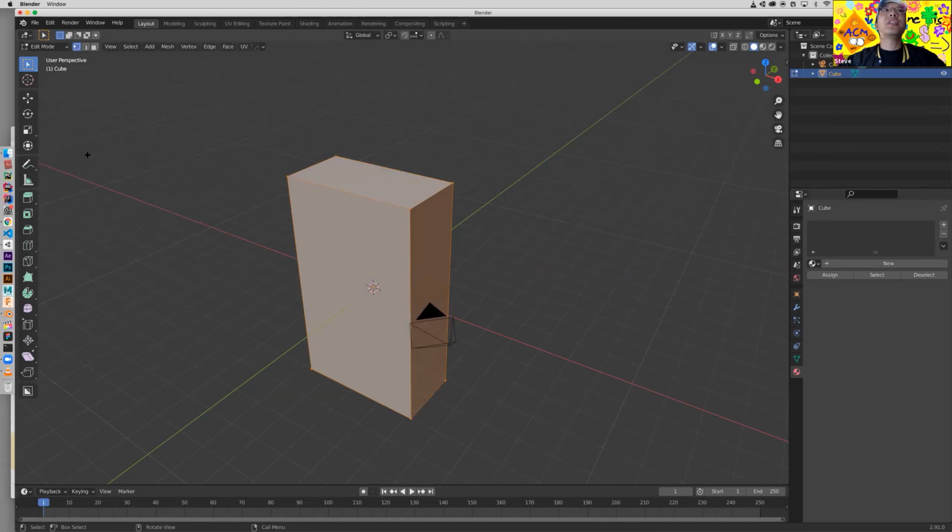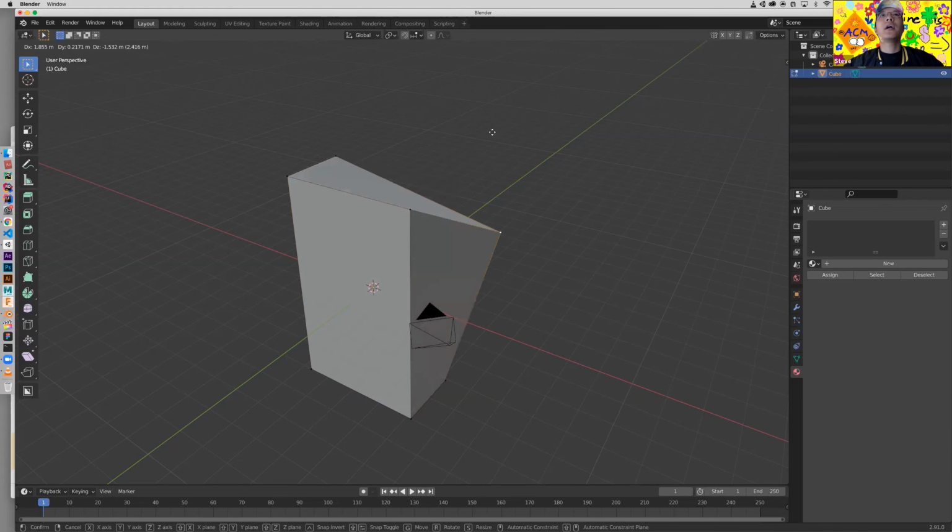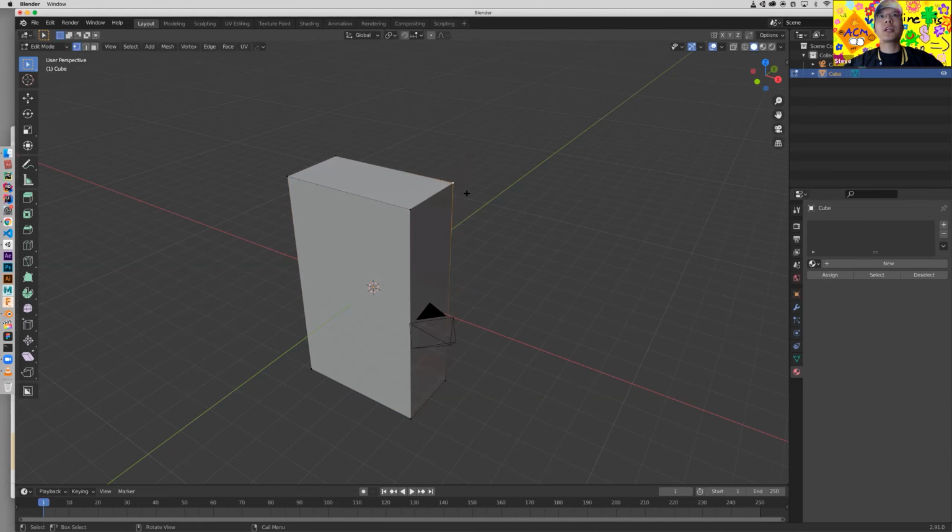And right now you can see the tool shelf on the left changes, and a lot of different components are highlighted. So we enter the edit mode. And on the top left corner, there are 3 different icons. The first one is the vertex selection mode. So in this mode, you can select individual vertices, and you can do transformations on those, maybe move them, rotate them, scale them. You don't want to do that right now.